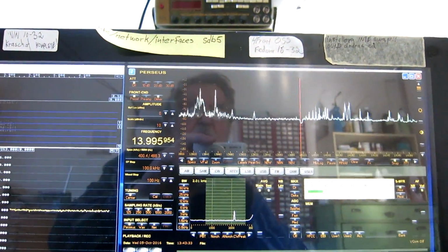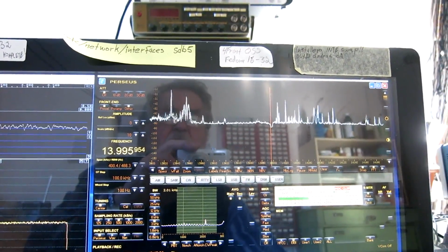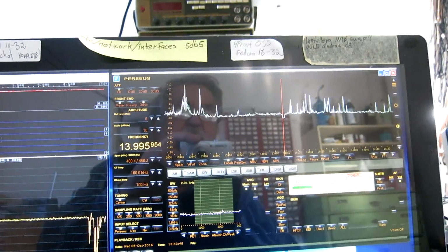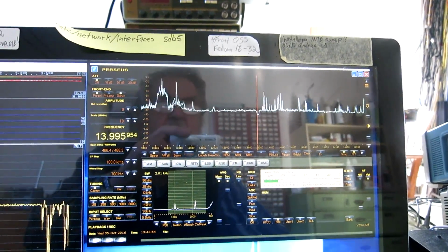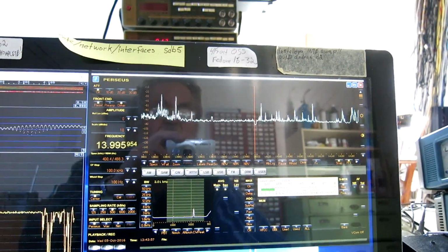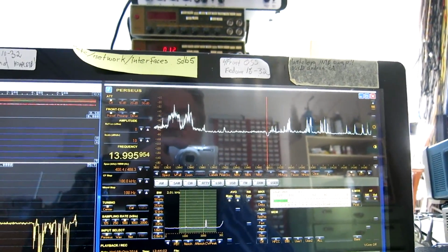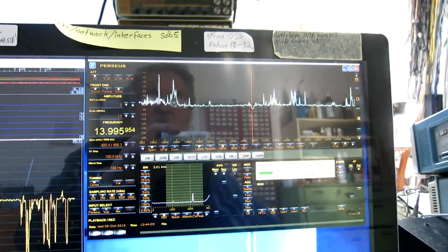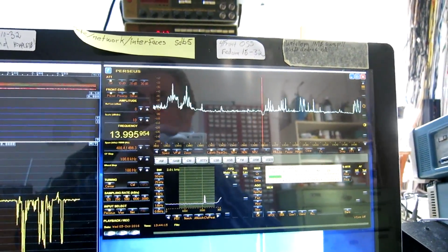I add 10 dB more signal now, and there is ADC clip occasionally. This one is heavily disturbed. So that was 10 dB, and I take away 3. Well, 4. So it seems with the pre-selector, the Perseus is about 6 decibels better.